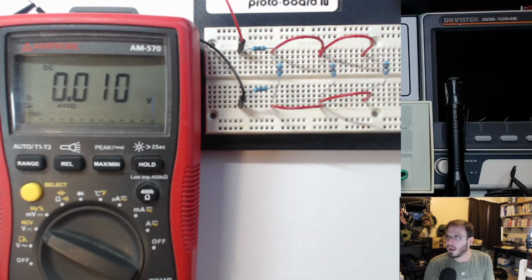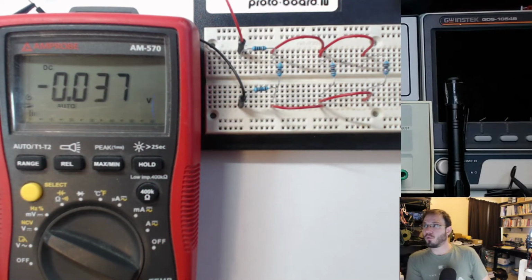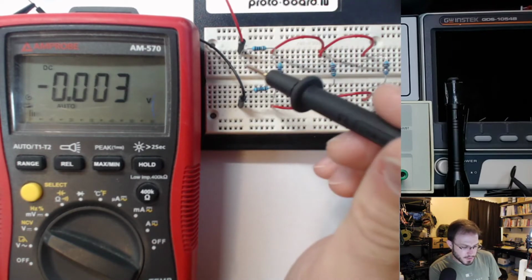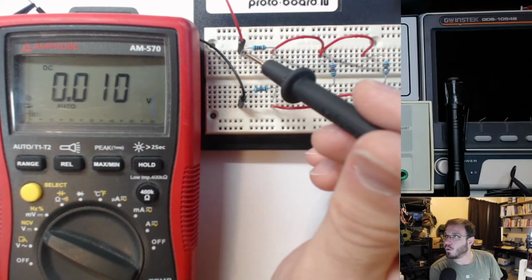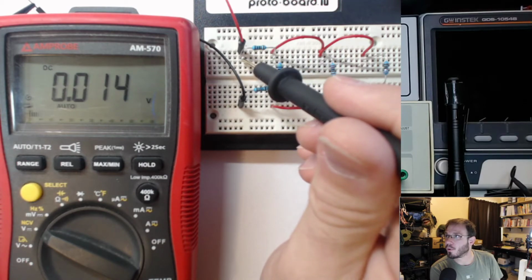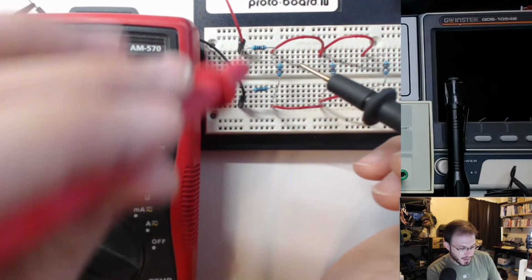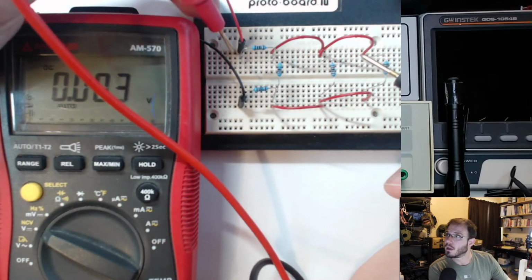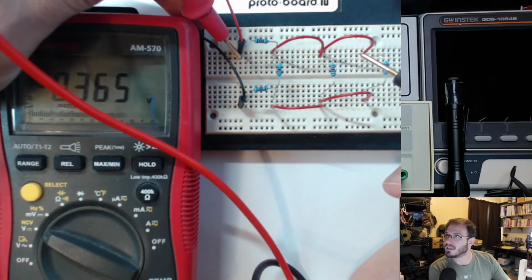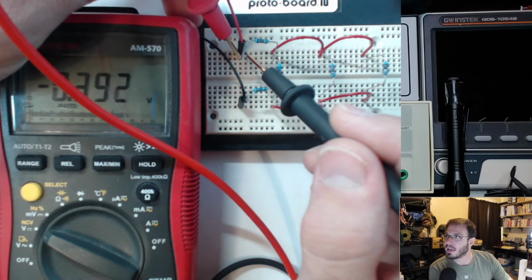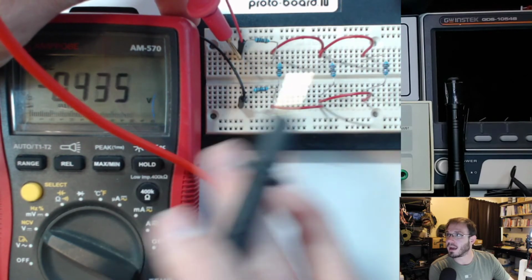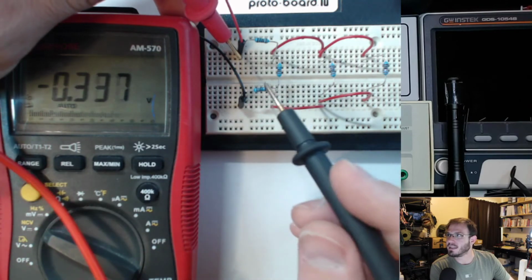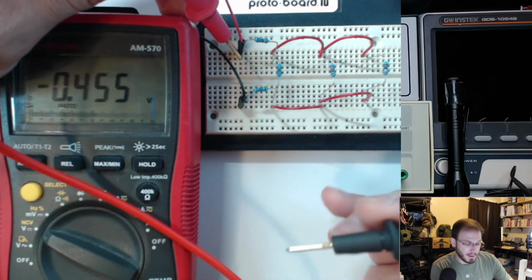Now, here's my advice. When you're probing a breadboard, use the point where the component plugs into the board. Where that plugs in, if I take my probe and I gently press down, I'm going to make a good solid connection with that conductor right there. Okay, so that's how I take a good precise measurement from my breadboard.